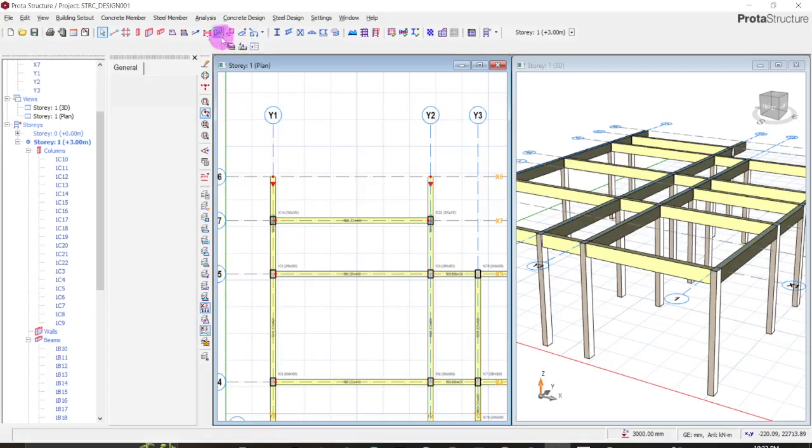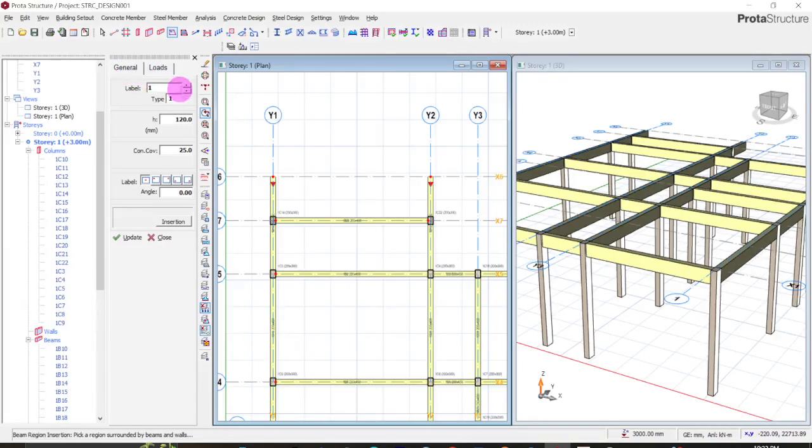So let's come to slab. Under slab, because we want to start the cantilever, we go to the option here, not that one. We come to the type of slab we want to do. We do type 12, which is that of a cantilever. Having type 12, we decide the height of our cantilever, which is 150, the same as the height of the slab.